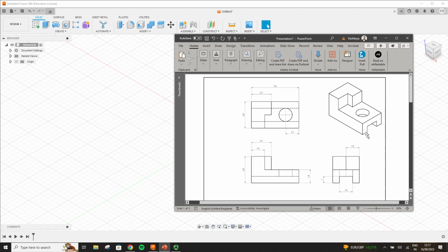So an easy way of designing this model, and that's how we are going to make it as well, would be to make this ledge and just extrude it straight, then make this L shape, extrude it straight, make a circle, make that hole. So those are some 6 steps that we can follow and very quickly make this model. So let's go and make the first one, and then maybe you will have a better understanding of what I mean when I said let's make a small plan. So I'll just show, and the first step, what essentially I meant is let's make this bridge shape.